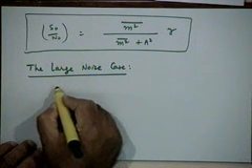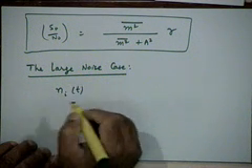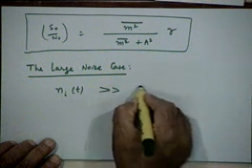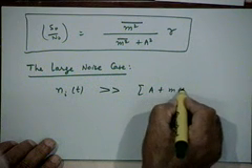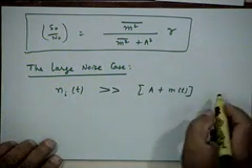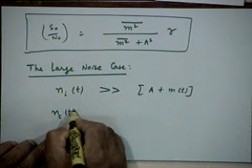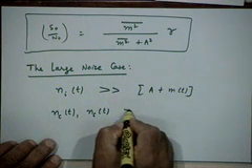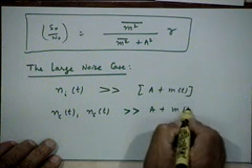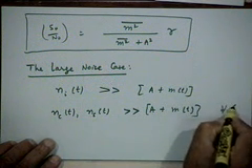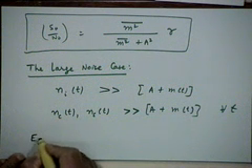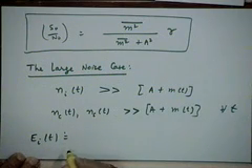And what do we mean by the large noise case? What we are saying is the opposite of what we said earlier: that your noise amplitude most of the time is much greater than A plus m(t). The received signal is much weaker than the noise, which essentially would imply that both Nc(t) and Ns(t) are much greater than A plus m(t). Now what can we say about the envelope? So E_i(t) would be approximately equal to,